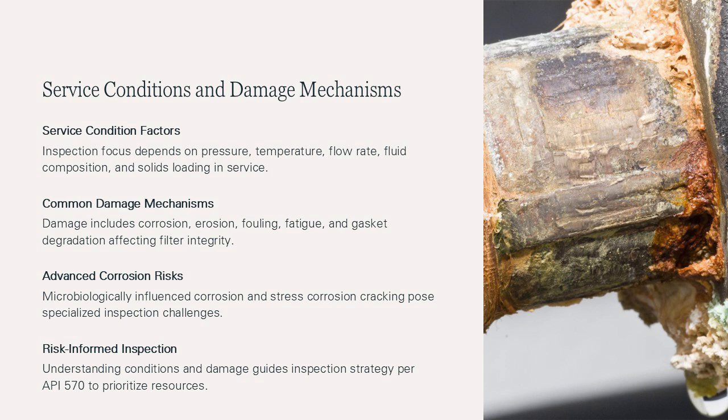Common damage mechanisms include general and localized corrosion, erosion from high-velocity or abrasive particles, fouling and plugging, fatigue due to pressure cycling, and gasket degradation. In certain services, filters may also be susceptible to corrosion under deposits, microbiologically influenced corrosion, or stress corrosion cracking.